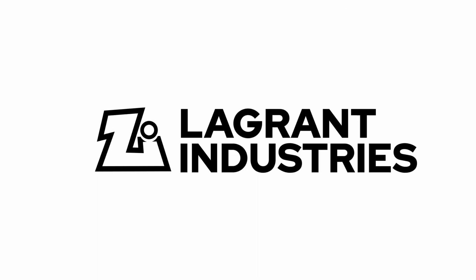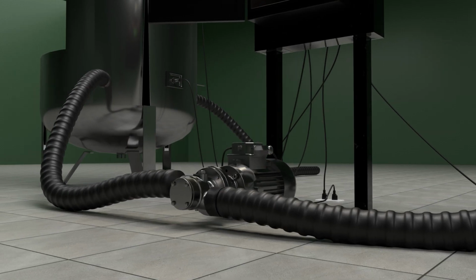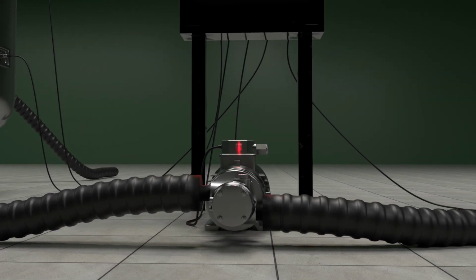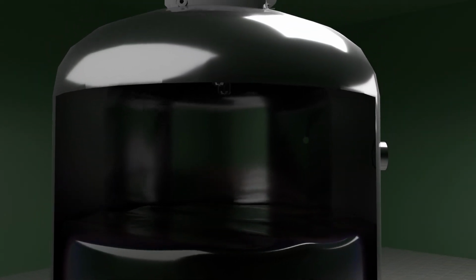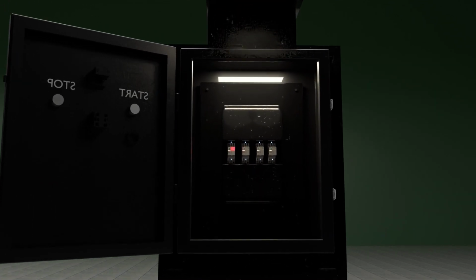Now let's look at this in an actual scenario. When the liquid level drops below the low-level switch in the mixing tank, the relay will switch and the pump will turn on. If the liquid level reaches the high float switch in the mixing tank, or if the operator presses the stop button, the pump will turn off. If the liquid level reaches the low-level switch in the supply tank, the pump will also shut off.